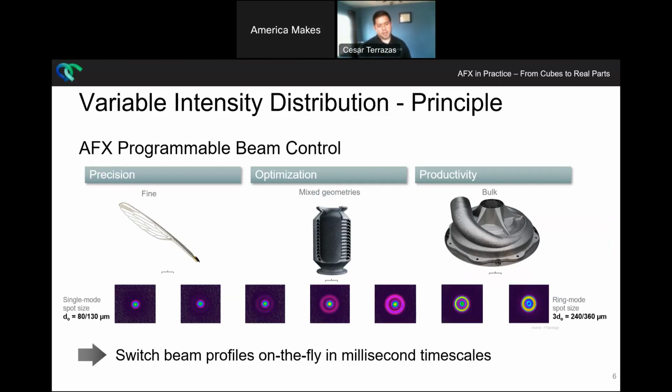Also interesting to mention is that through Aconity Studio, we can flip through any of these emission modes almost on a millisecond scale. That means that within a single vector that is scanned, you can modify the emission mode, altering the characteristics of that beam and the effect that is going to be seen by the powder.